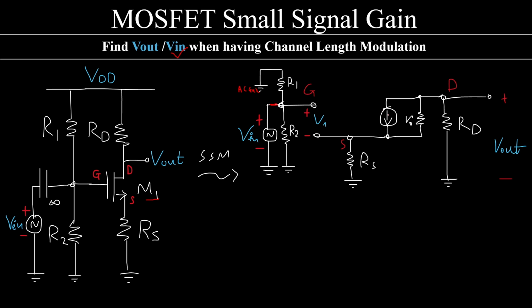How much current is this dependent current source producing here? Well, it's nothing but V1 gm. Step number 1: name all of the currents. There is a current flowing upwards from here. How much is it? Well, it's going to be minus Vout over RG.